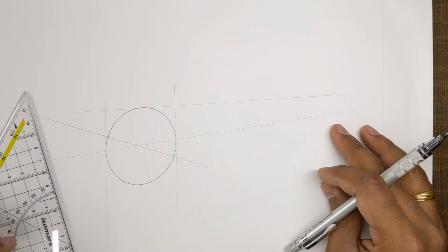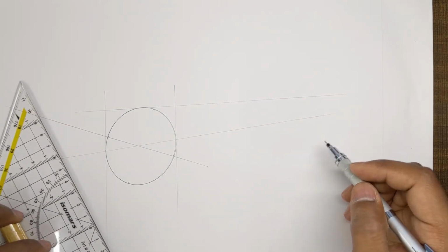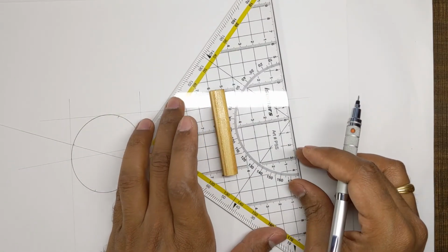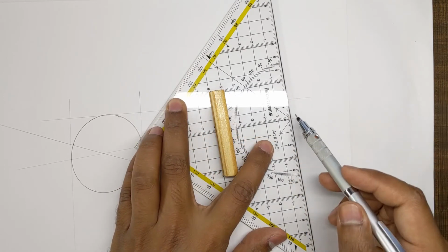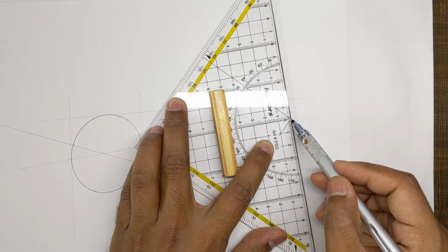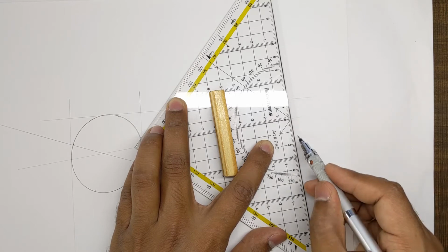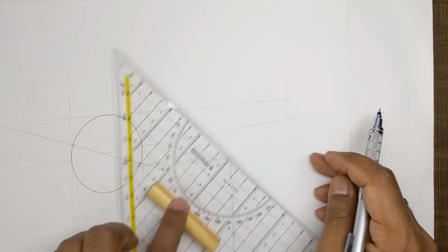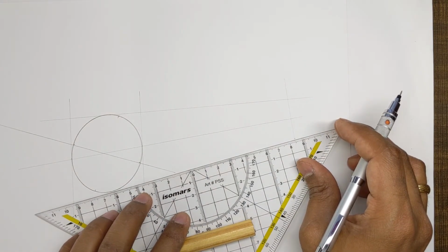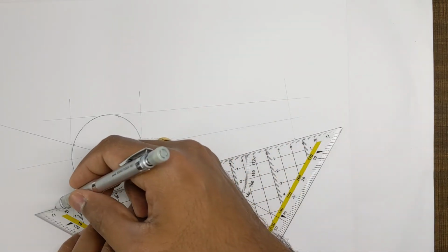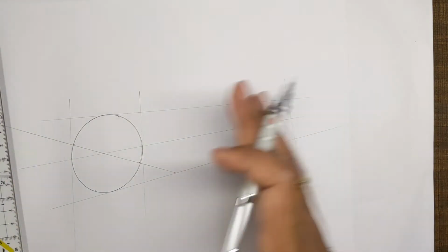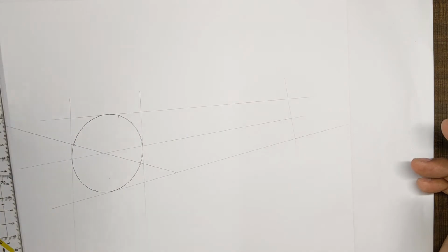This looks good. Now, to achieve the same amount of convergence, one trick that I use is from the center line, just drop in a perpendicular line like so and see what is the distance at any point. So it is 1.5, 1.6. So here also it is 1.6. I have my point over here, and from this point just drop in another tangent line to the ellipse. So we have our plane, the plane in which we want to replicate our side view.